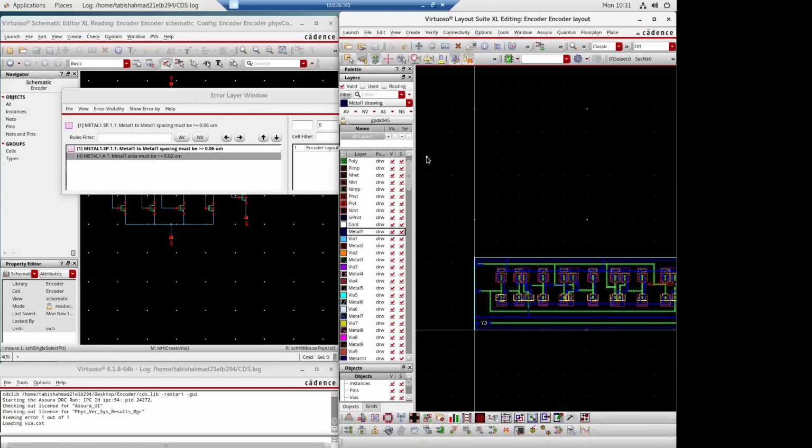If according to the layout they are correct, then no DRC error will be there. But if according to the schematic the connections are not proper, or you have connected the wrong things, then an LVS error will be shown. I will show you the LVS error check in some time, but make sure that you are making the layout according to the schematic. Okay, now just a second.